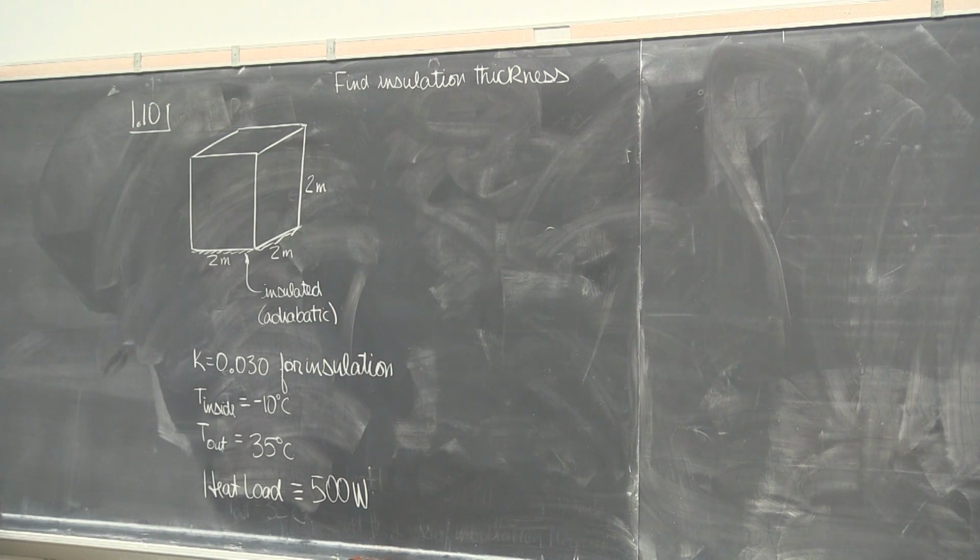He didn't tell us the air temperature. He didn't tell us the convection coefficient. So we're not supposed to be considering convection over there. He didn't tell us the emissivity of the insulation. He didn't tell us it's in a big room, so we're not supposed to use radiation. Well, left with what? Obviously, we're left with conduction. Okay, this is a conduction problem.